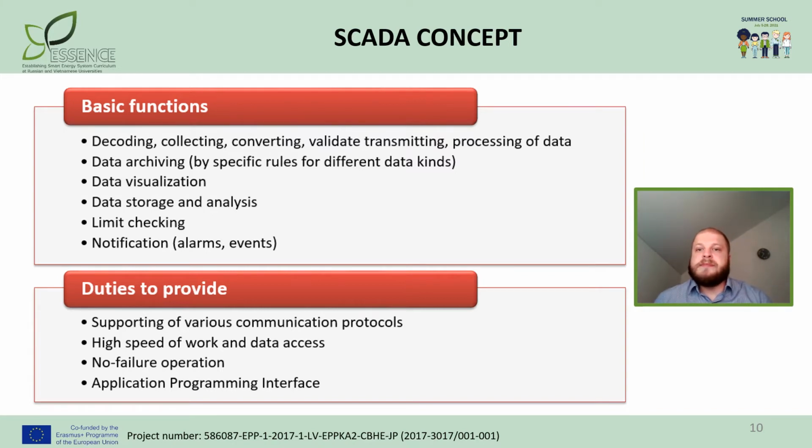First of all, the systems you need to monitor, I mean the power systems, are much more complex than just one machine with one output like capacity or electric current. So a real-life SCADA system needs to monitor hundreds or thousands of sensors. Some sensors measure inputs into the system, for example, water flowing into a reservoir for hydropower plants. Some sensors measure outputs like voltage, current, and power system frequency.